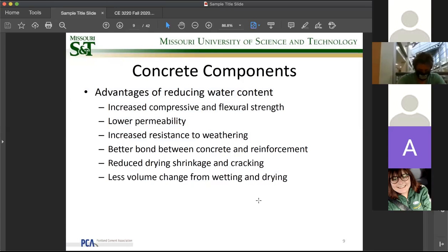Now, you have to figure that if you have less water, the concrete can set in a very fast time, right? So normally, without any retardation agent, with a very low water ratio, we're talking about 0.2, 0.3, extremely low, the concrete can set in 3 hours. And that's not enough for large structures, okay? And for high-rise buildings where we need to pump concrete up 20 floors or more, this simply is impossible.